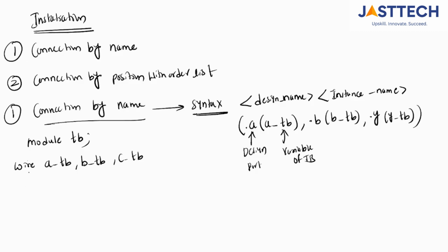Okay. And next, inputs normally you can declare with reg or wire. Here you can declare with reg also. Okay, and output should be wire data type. So output should be what? Wire. Net data type means wire y underscore tb. This is the output.